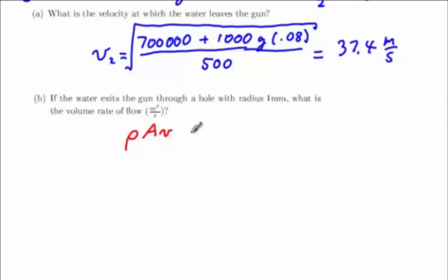If the fluid is a gas, it's very important to use this quantity, since the gas can be compressed and have varying densities at various locations. However, it is more common when the fluid is a liquid to use the simpler form, area times velocity, since area times velocity is cubic meters per second.